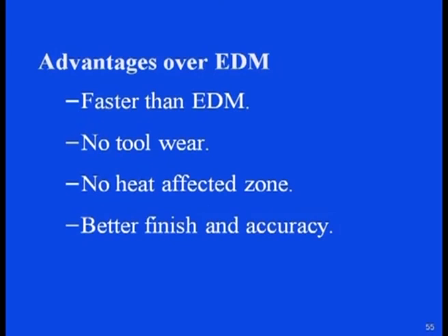The other advantages of this ECM process over the EDM are: it is faster than the EDM process, as we have seen just now. It could be as high as 10 times. No tool wear, no heat affected zone, which is very common in case of EDM. There will be a large heat affected zone in the cutting area in case of EDM. Also, better surface finish and accuracy can be obtained in case of ECM with respect to EDM.